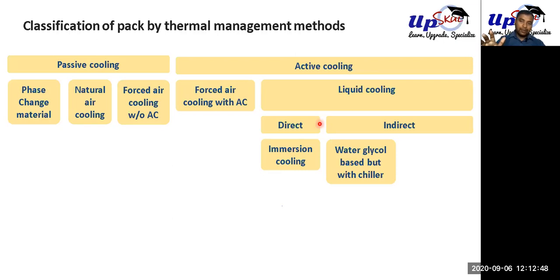On the indirect cooling, we can use any kind of electrolyte, any kind of coolant. Previously we were limited to only those coolants which are not conductive, which are dielectric, not corrosive, not flammable, and all kinds of things, because they come in contact with electric components all the time. So there were lots of criteria to meet. But now we can just use our plain good old water. In a car, we never use only water. We use a mixture of glycol and water.